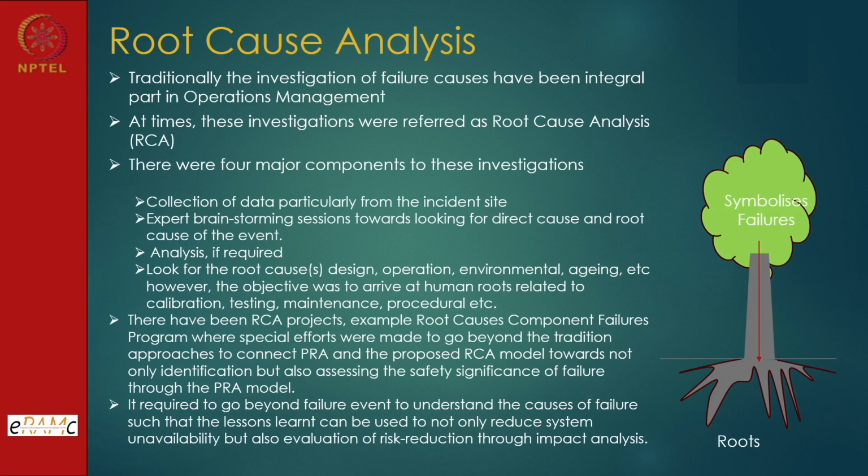Suppose there was a bearing failure, a very important bearing failure. Any symptom which can help us in understanding the event is important, because the plant will come to a halt, and if it is a safety rated equipment, then it becomes a safety issue. So all the information is collected and arranged in chronological order. It's very important. Based on the symptoms that are available in the control room at the site, arrange them in chronological order, and then expert brainstorming sessions happen. And some analysis, if required, also forms part of it.